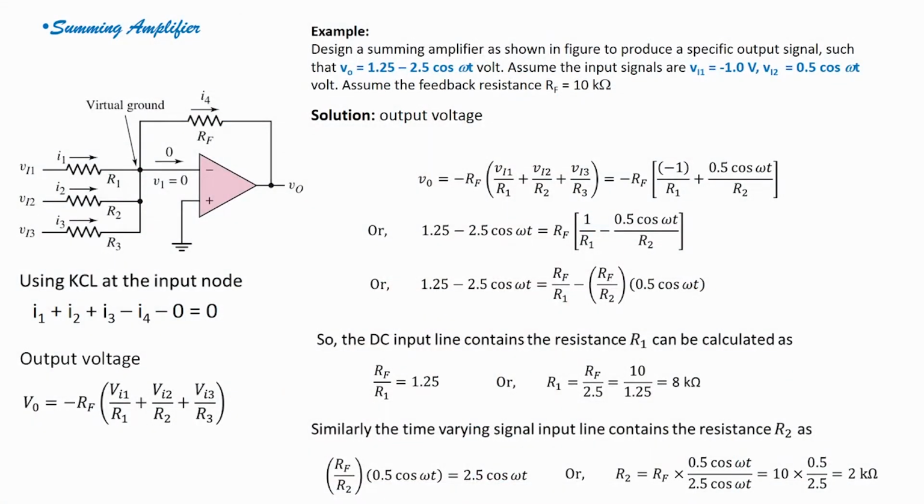Okay. So, when you see the circuit, if you come back on the screen, you will see that we are using an inverting amplifier. We have a feedback resistor, but instead of one input resistor, you have 3. You can have n input resistors. So, n inputs, and the output will be the summation of all the inputs. Okay. So, how can we do that? It is written over here.